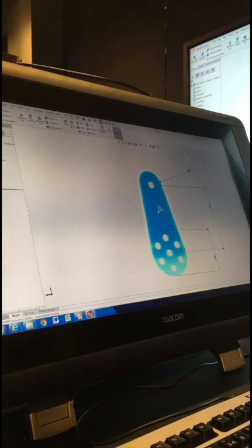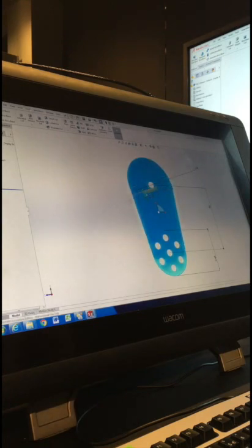The other thing with Instant 3D, see this little blue marker here, this little blue dot on the end of that dimension? I can click that and see this ruler that comes up. I can actually just drag to adjust that size. Now I can just do that sort of freely over here, or if I move my cursor to the ruler, I can drag along certain increments, 50, 60, 70, 80, etc. So you can see how things would change just by sort of dragging and moving.